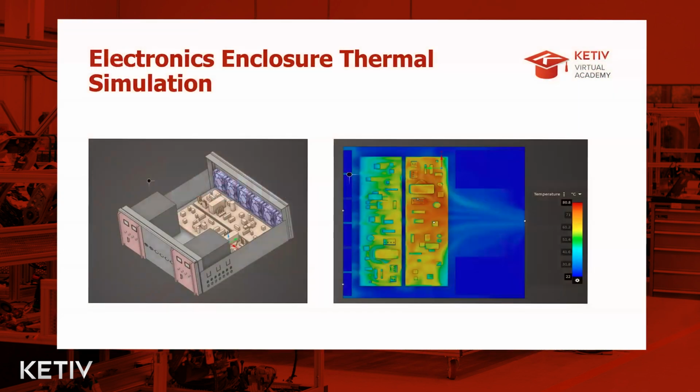And I'll start with the problem statement slide and then switch to the GUI. This is basically an electronics enclosure over here. What I'm going to do is create a watertight enclosure around this and assign some heat loads and some fan velocities to see how the flow propagates in this particular domain. And then we'll see what kind of post-processing results we can get in Discovery. Again, if you have questions, feel free to leave that in the chat box. I'll definitely get to it later on.